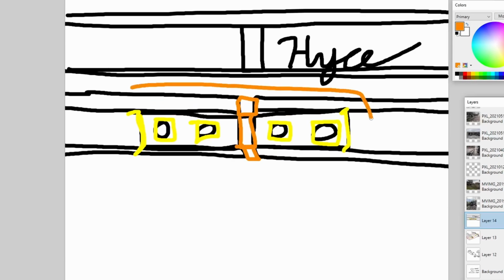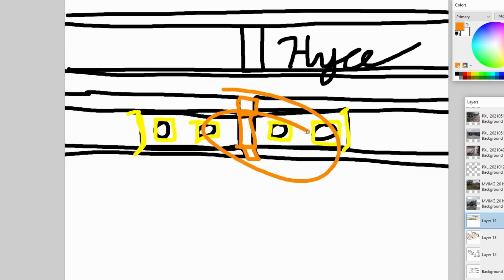So there is still a time and place for these, but typically they try to have what is called continuously welded rail, or CWR. So typically you'll see on track drawings things like, oh yeah, it's 136 pound CWR through this railroad. Okay, that means that it's 136 pounds every 3 feet, all the way down the railroad, except for when they have to put these in for the signals.